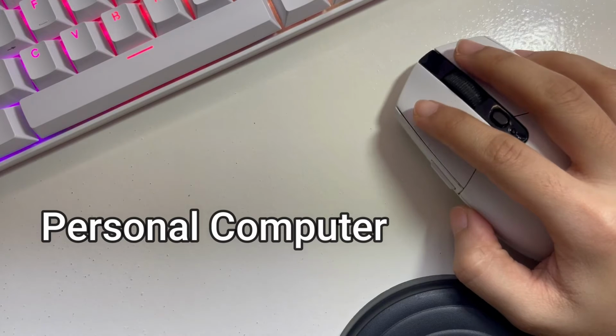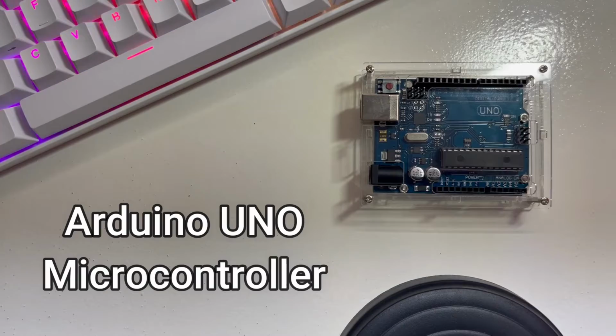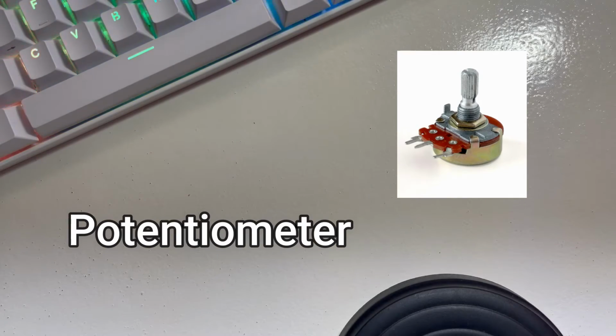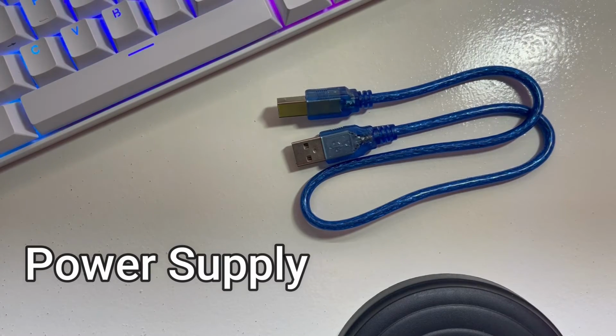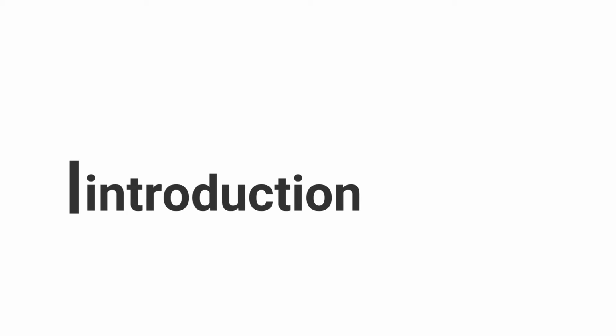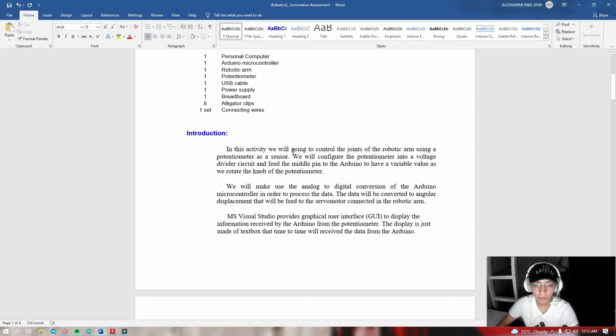Equipment and materials: a personal computer, one Arduino microcontroller, one servo motor, a potentiometer, one power supply, one breadboard, one set of connecting wires. Next, introduction. In this activity, we will control the joints of the robotic arm using a potentiometer as a sensor. We'll configure the potentiometer with a voltage divider circuit and feed the middle pin to the Arduino to have a variable value as we rotate the knob of the potentiometer.